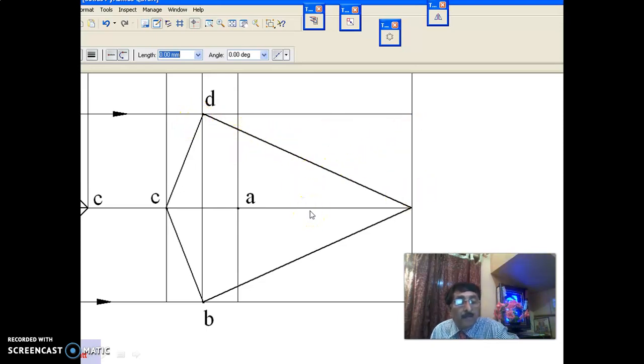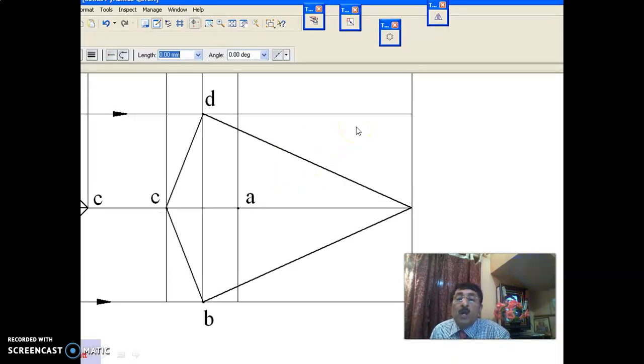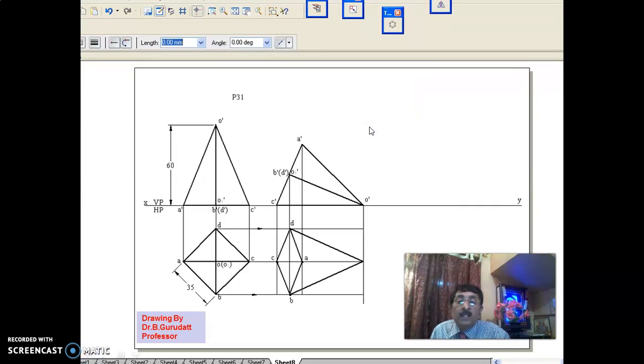As you are aware, in this problem, when you are looking from the top, base is nearer to the observer, base is exposed. Hence, what you do is, after outer boundary, as a second step, since base is exposed, base will be darkened. As a result, now you have 4 plus 2, 6 edges. You are looking from the top. In the third step, you have to complete 2 more edges. 6 edges are already over.